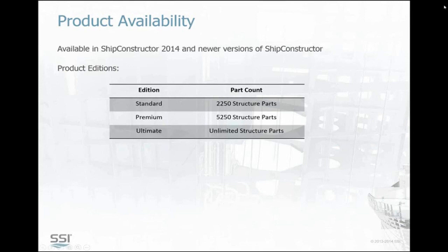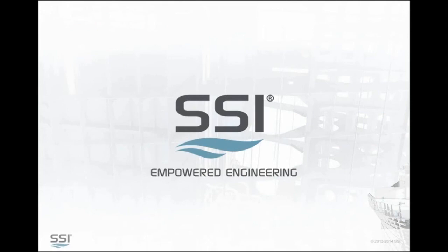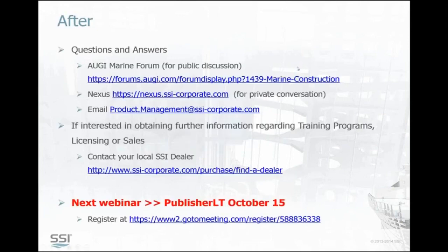If we don't have any more questions, do you have any more that we can answer right now, Jason? Yeah, so it says, can we put name on equipment for a GA or machinery arrangement? And that's yes. You can create a bill of materials that shows the equipment stock or a tag number, and create labels automatically for those using an equipment collector in a bill of materials. So that's quite easy to do.